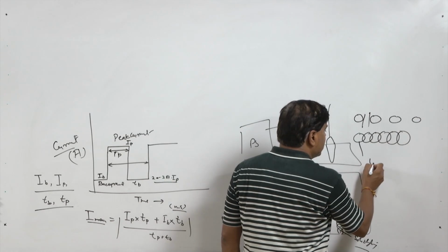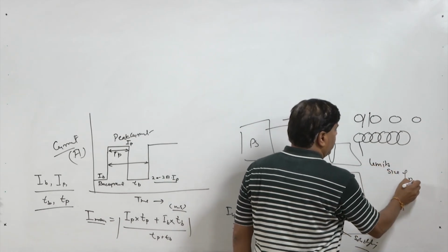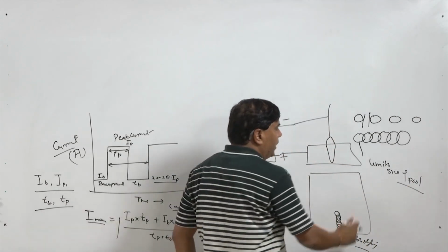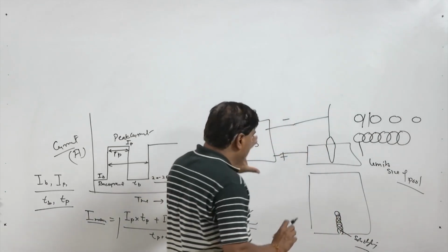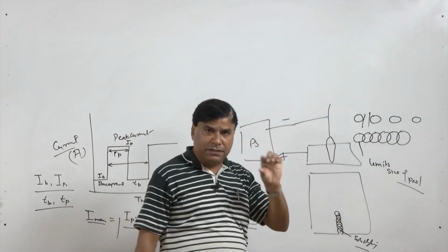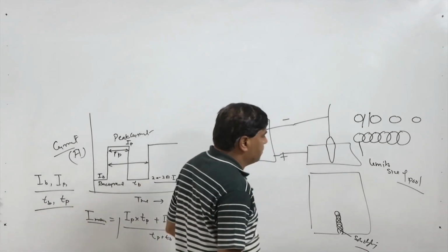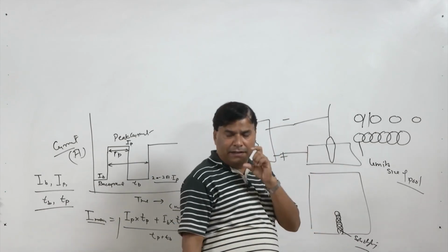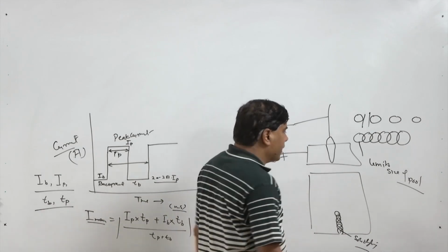Advantage of this is what? It limits the size of the pool. So, the maximum grain size is limited to the size of the pool, and this combination as a whole reduces heat input for melting a given thickness of the plate. So, whenever pulse GTAW is used, it penetrates deeply, but using a lower amount of heat.